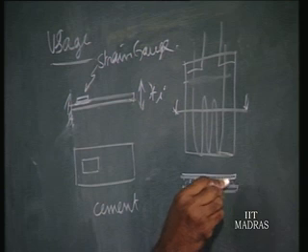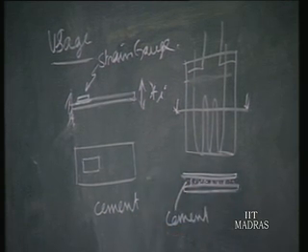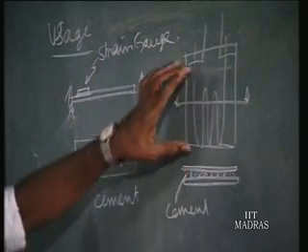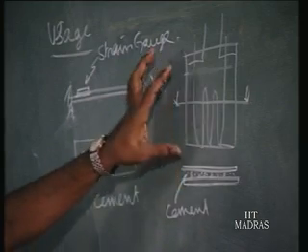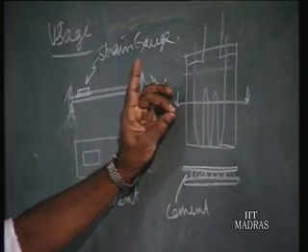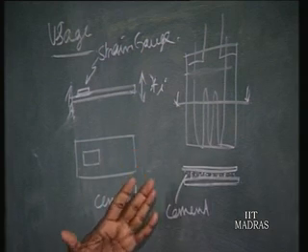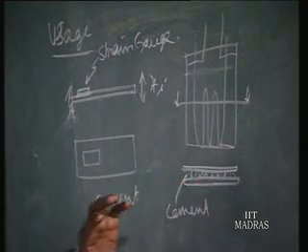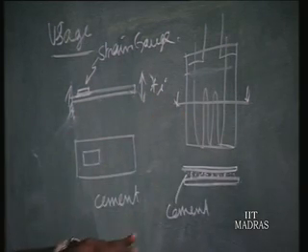Here also we have cement, completely filled. There is no gap between the wires, all the space is filled up with the cement. Because of this construction, the wire can also take up compressive strain. A free wire cannot take compressive stress or strain because it will buckle, but here there is no space for buckling as it is manufactured. So the wire can take up both tensile as well as compressive strain.